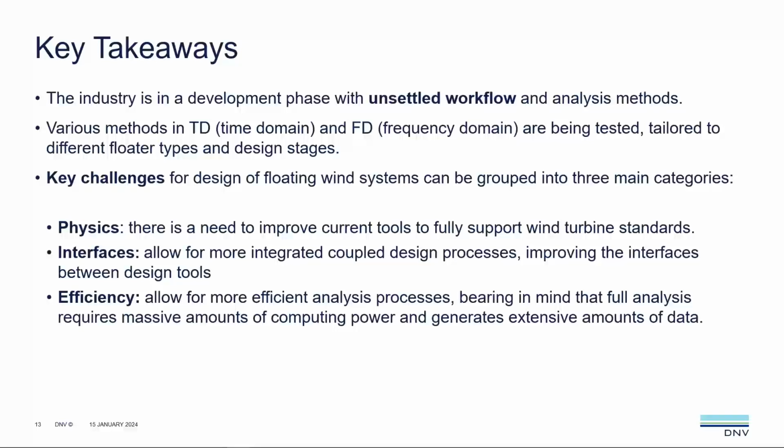Thanks. Interesting question. So the first one about this misalignment. Especially for these single point mooring systems that can weather vane, for certain load cases, for example DLC 1.4, where we're looking at direction change of the incoming wind, we see that the change in position, if we're looking at the yaw angle, can be significant, 30 degrees or more.